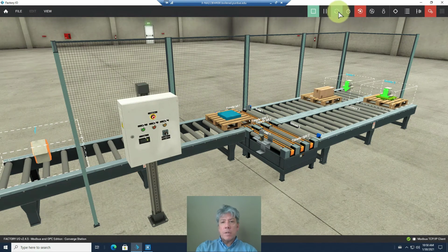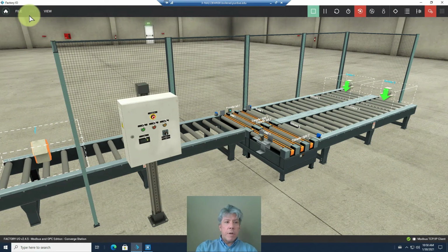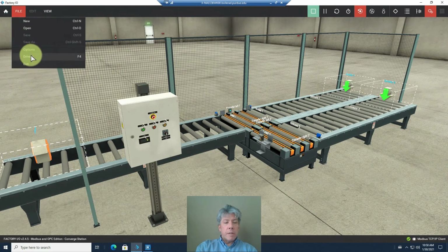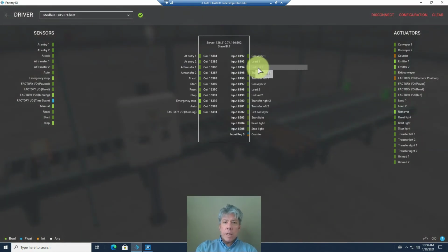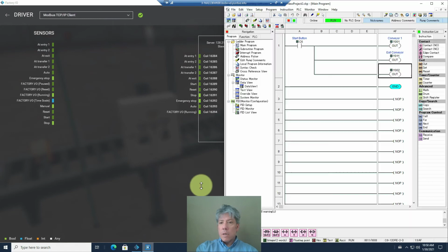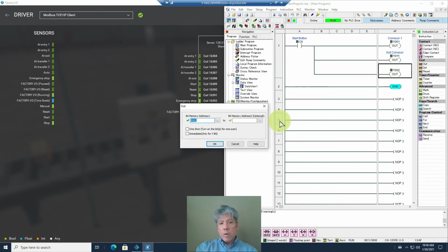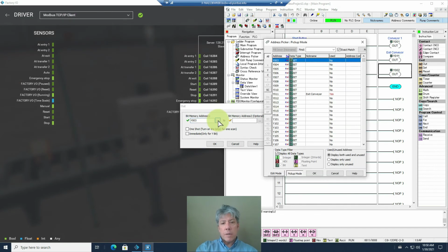So we'll reset the simulation, and if we look on the drivers, unload is going to be after. So we've got 8192, 8193, which is Y002. This must be 8194, Y001, or over on the Click it would be Modbus address 8195. But it's Y00, let's see, 3. So that's fine. So just for fun, we'll make this Y003. And I realize I should have named these. Probably just match whatever's already there.